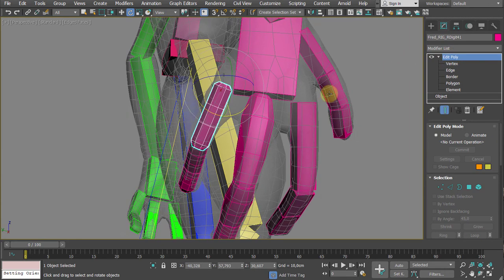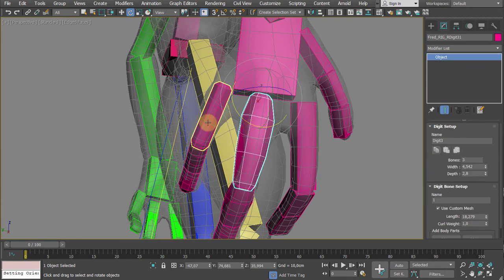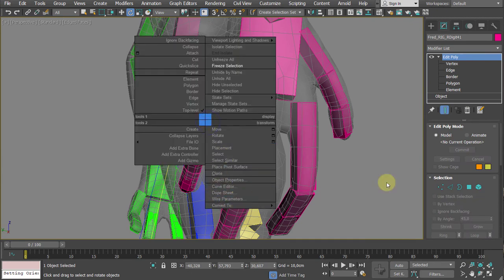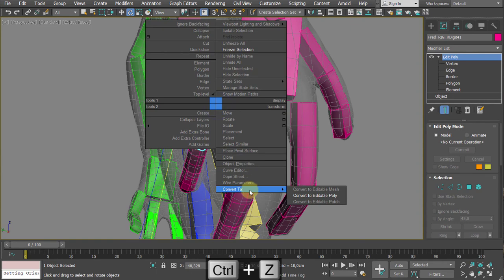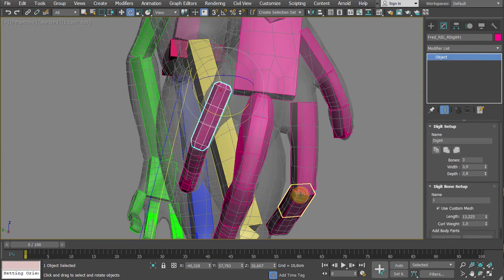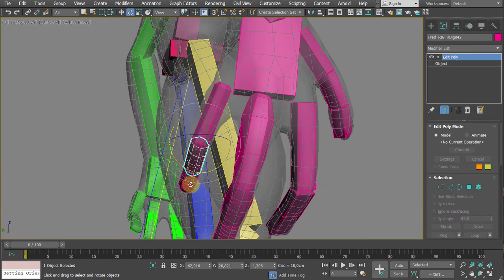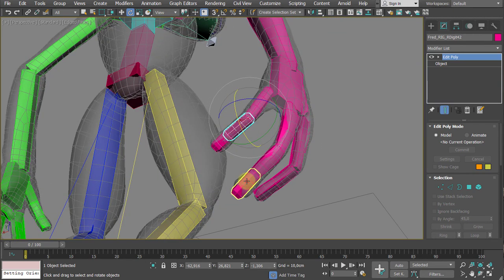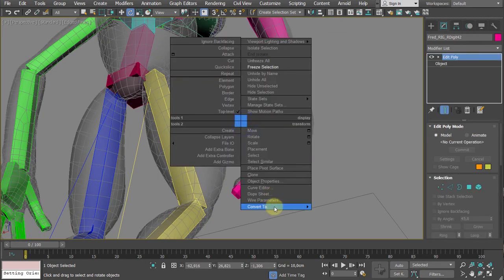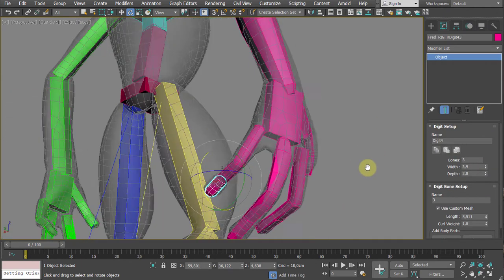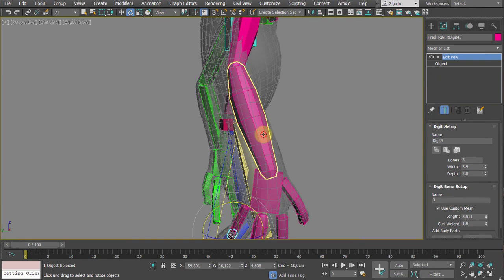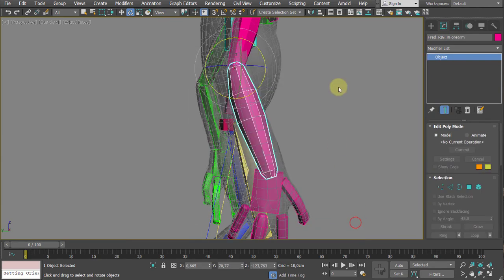So the trick, if you see this bug, that you are selecting the model, converting it, you can actually convert it into editable poly, and it will flip. Just press undo and do it again. Convert editable poly. Alright? I don't really recommend doing these conversions simultaneously. I think it's better to do them one by one. And time after time, don't forget to use a hold.